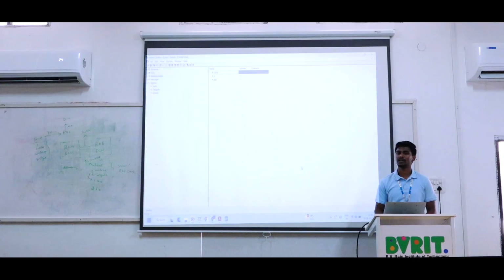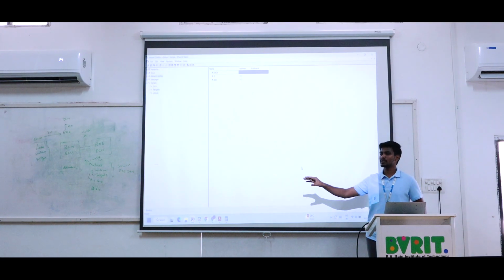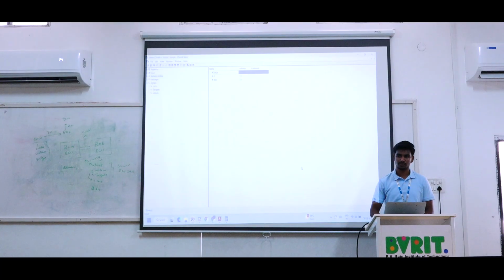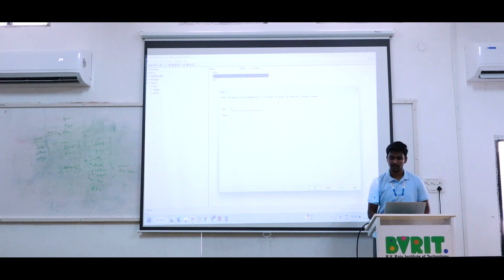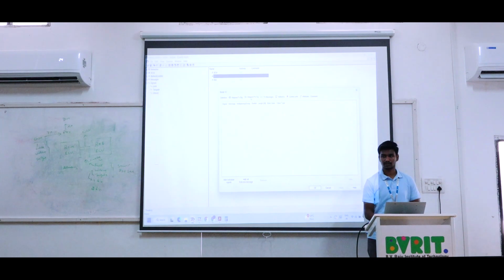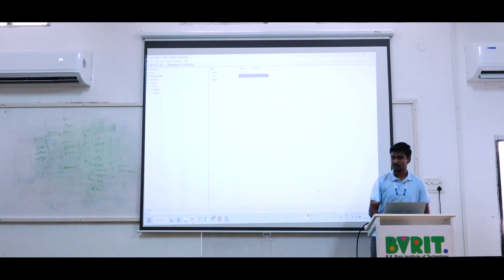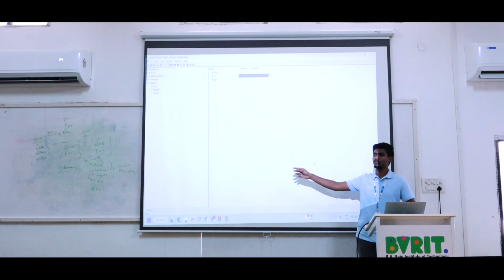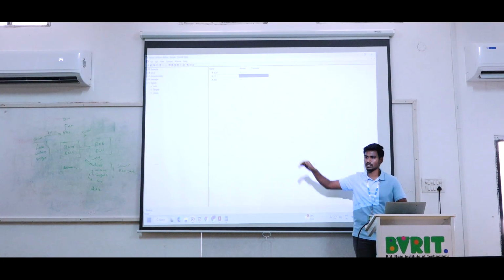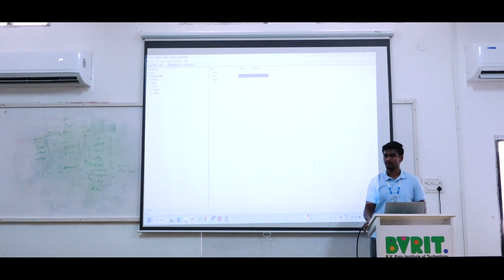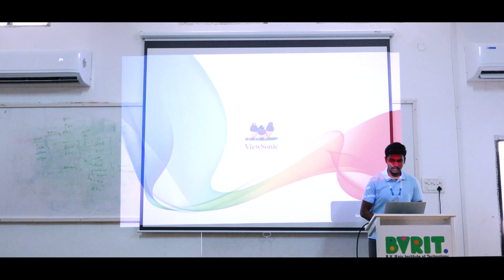The one more receiver is the instrumental cluster. Parallelly, the output we have received with the body control module, we can see it under the instrumental cluster. So we go for IC and then double click. We have mapped the same signal on the RX also. Map the RX, then add the individual signal message and anything else. Now this lock unlock data is received by both the body control module and the instrumental cluster unit at the same time.